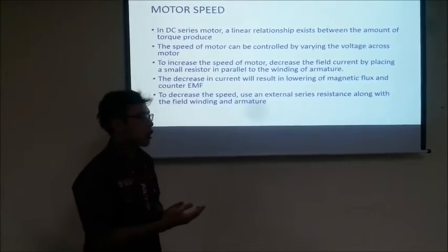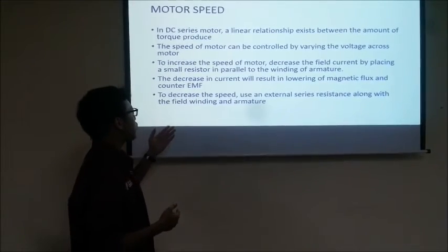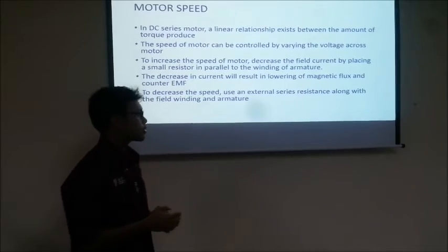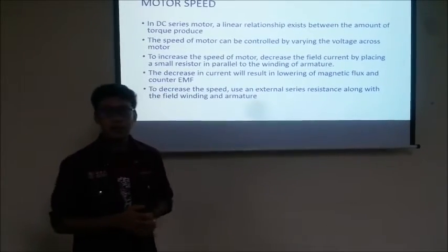Now I'm going to tell you how to decrease the speed of the motor. To decrease the speed, we use an external series resistor along with the field windings and also the armature.